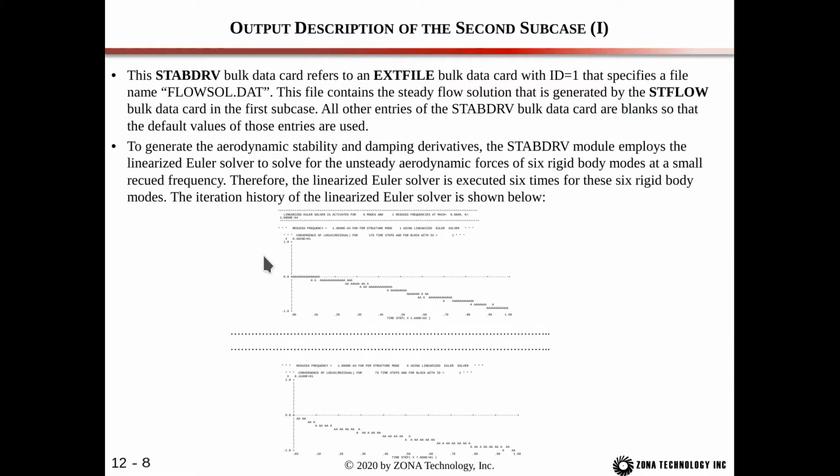So we've cropped out a section of the output file, and here we have the convergence history of 2 of our modes. So this is mode 1, and then this one here is mode 6. And note that mode 1 only ran for 170 time steps. And our second one only ran for 79 time steps, and that's because we achieved the 4 orders of magnitude reduction in residual in only 79 steps. So after 79 steps, the computation terminates and carries on.